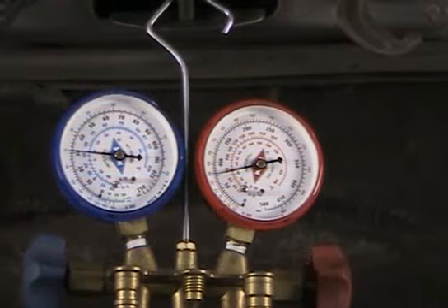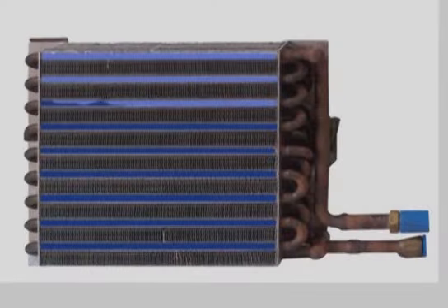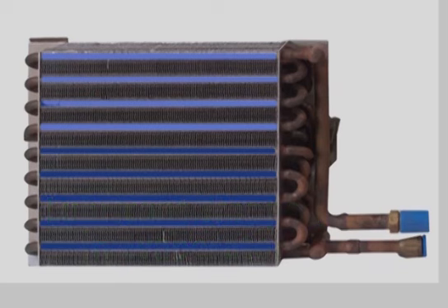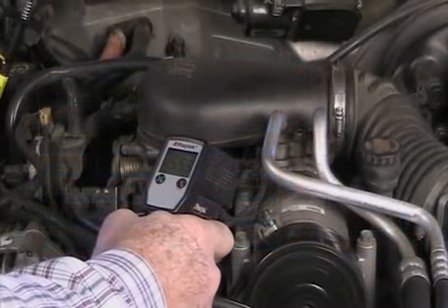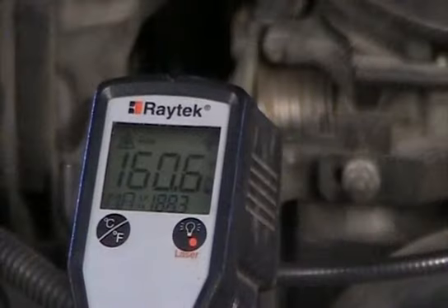As the refrigerant leaks out of the system, the liquid level drops in the evaporator and the vapor pressure can no longer push the lubricant out. At this point, the evaporator is trapping all the lubricant, and refrigerant vapor exiting the evaporator is much warmer, leaving the compressor with less lubricant and no cold refrigerant vapor to maintain proper operation, and it ultimately fails.